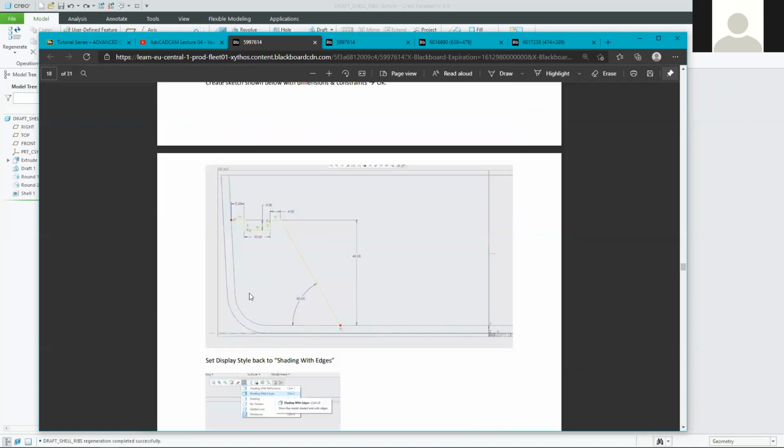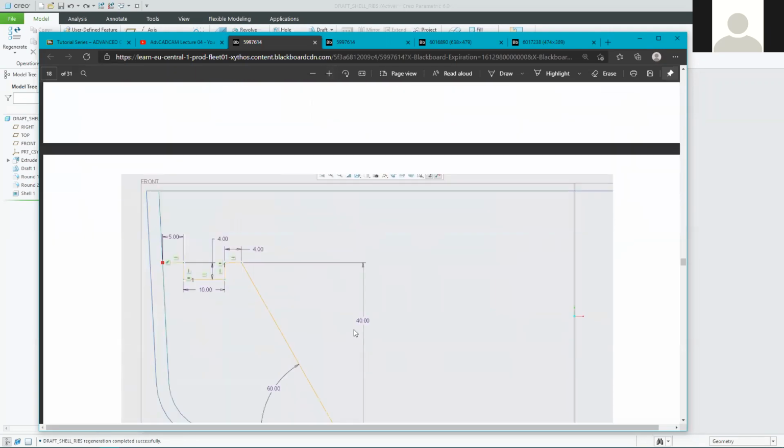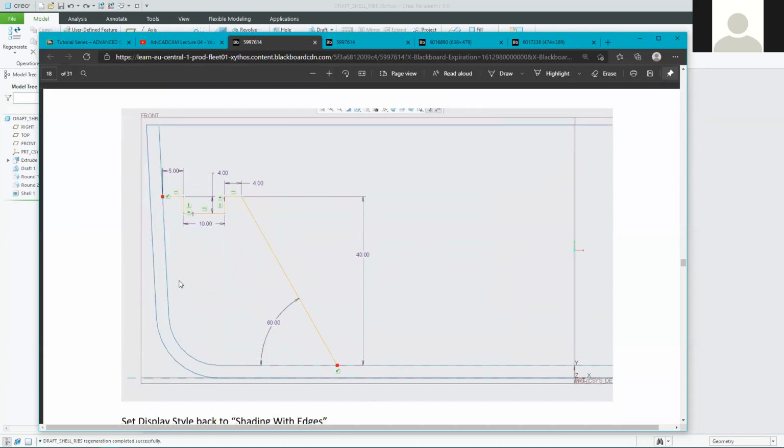And what we're going to create within that sketch is that sort of shape. So hopefully you can tell what we're looking at there. So here's this upright side wall of our box. So that is 1.5 millimeters thick. It travels down at a 10-degree angle there, so you can see it. It's got that lower round feature on it. It's still 1.5 millimeters thick. Then there's the base of the box there.